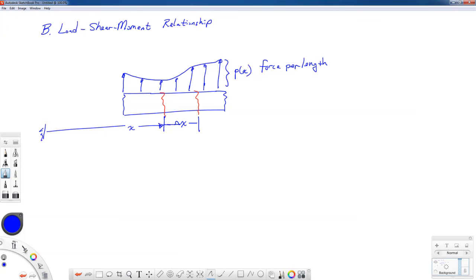Now this diagram that I have is not a free body diagram, but I'm going to take a free body diagram out of this beam schematic and sketch that. So I'm going to indicate the cut for the free body diagram with these squiggly lines, and then the top and bottom surface of the beam by these blue lines. And on this I have the section of this distributed load. Maybe it does something like this. And I'll indicate the load over here.